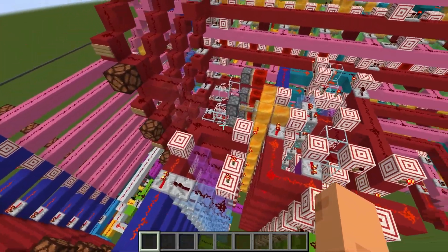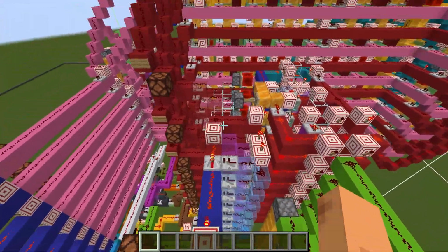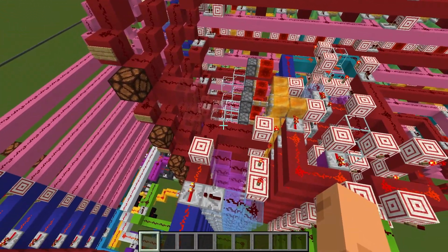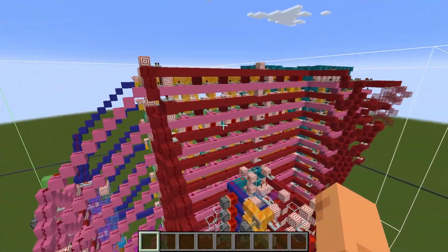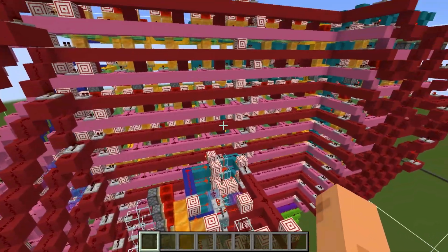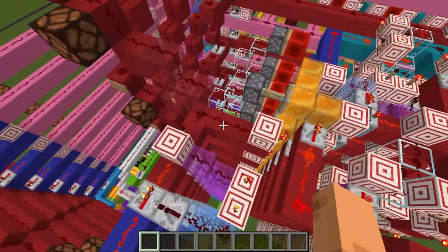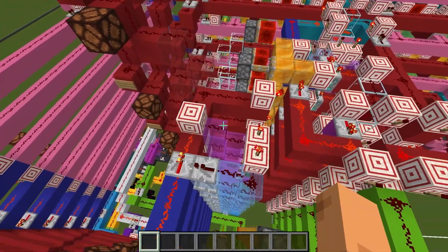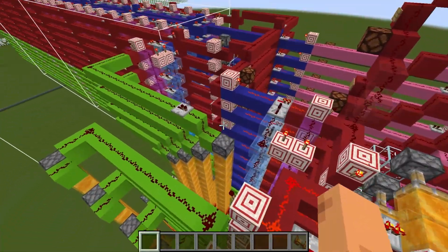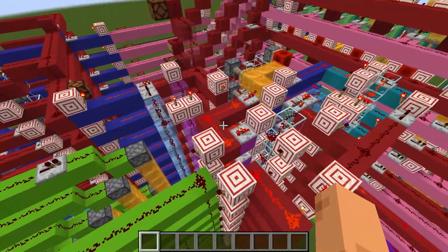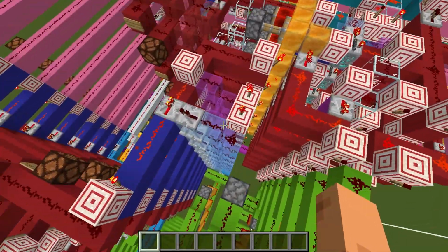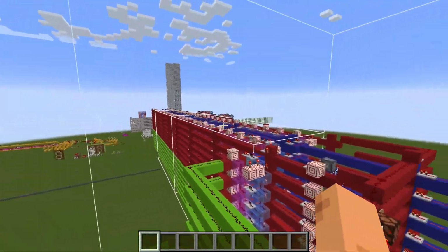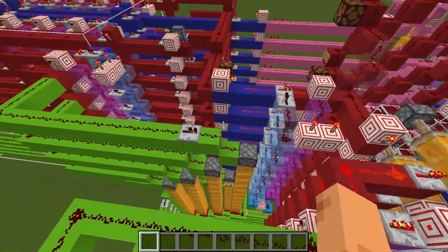And other than that, the accumulator part is basically just keeping track of a temporary piece of data for our first input into our ALU. So that is used to keep track of a loop counter, keep track of the indirect memory address for those instructions, various functions like that. It's basically a temporary buffer, effectively. A placeholder while we're working with some other piece of memory. We have the placeholder accumulator to do that.